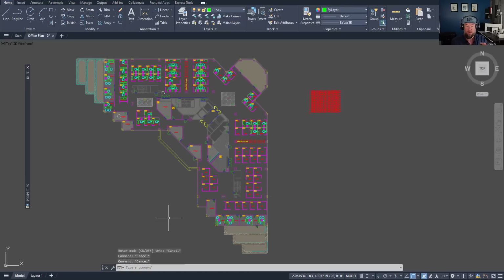Basically, it's just going to keep everything in AutoCAD looking the way it does, and then when you type in regen, it'll update and refresh everything in your views and layouts and that kind of thing. So this can just save you some compute power if you're working with a large drawing that's kind of struggling on your computer. That's probably the most useful case for this one.